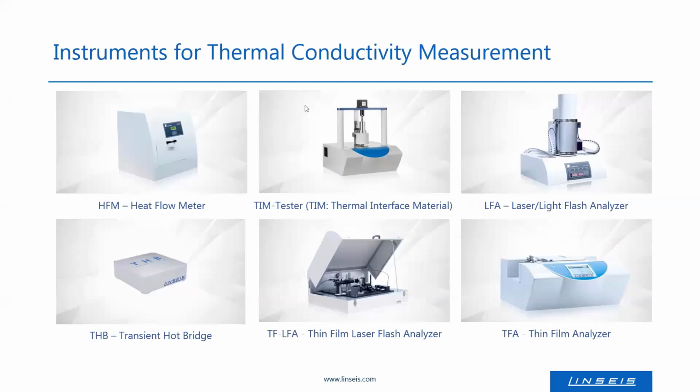But today's topic is thermal conductivity. So there are mainly 6 instruments I want to show to you. Those are the heat flow meters, the TIM tester, TIM standing for thermal interface material. You'll see later on what this is. LFA standing for laser and light flash analyzer. The Transient Hot Bridge, hot wire technique. And 2 instruments for the characterization of thin layers, the thin film laser flash analyzer and the thin film analyzer.